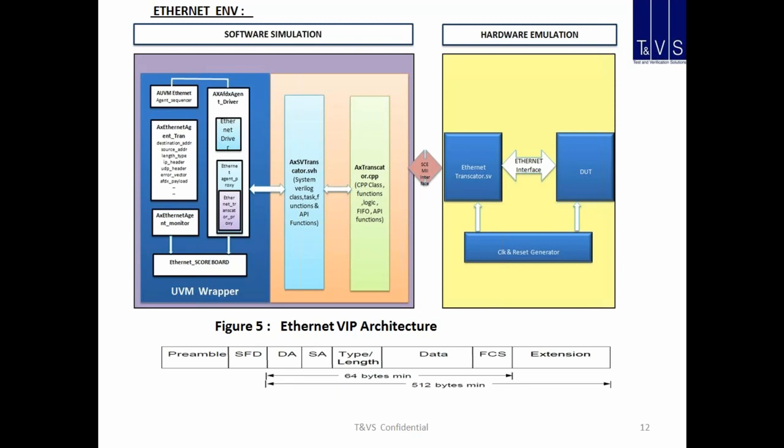The checking mechanism should be on the other side, which means your UVM side, where you can do all the stuff in sync. Because when you are using C, DPI and UVM and then SCE-MI, maintaining at the C level is really a challenge. Things become out of sync with regard to the clock and all the stuff which is running on the other side.